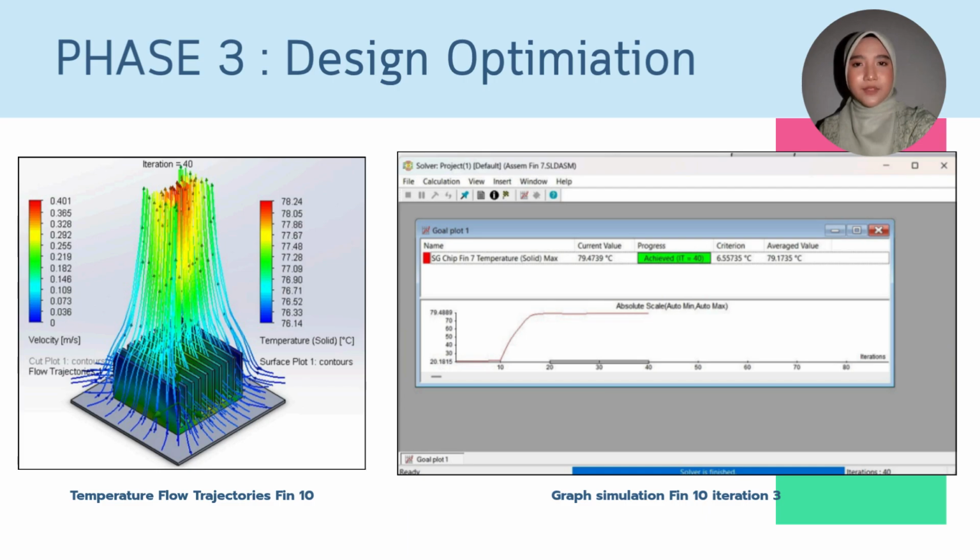This was a critical finding for us, as it suggests that simply matching the fin count of the base case with thicker fins under higher heat loads does not necessarily yield additional cooling benefits. It highlights that the relationship between fin count and temperature is non-monotonic in natural convection.